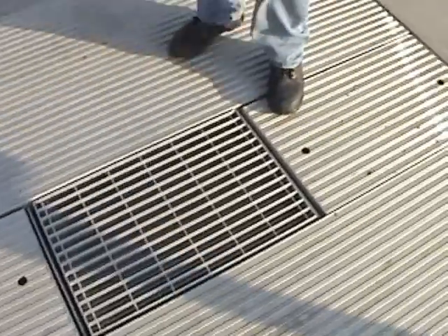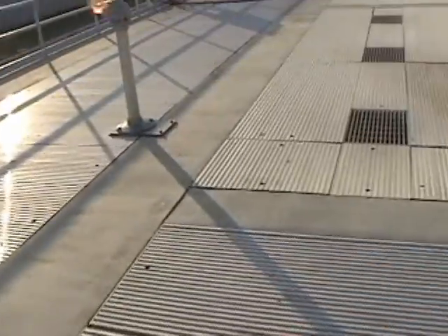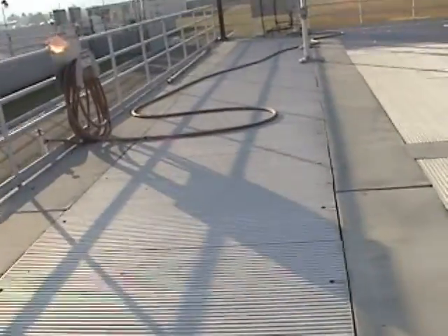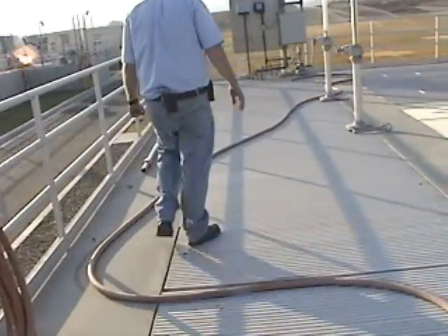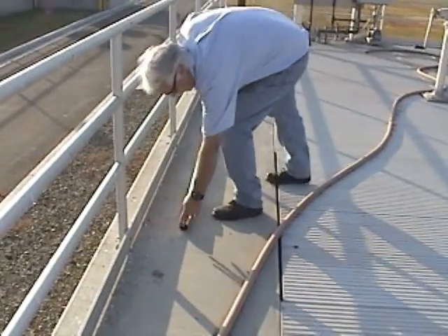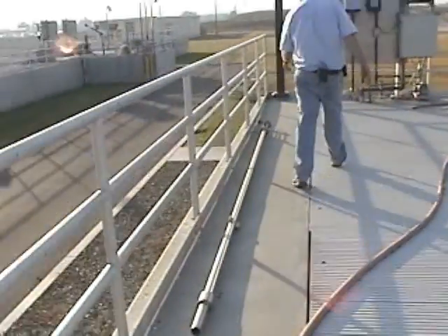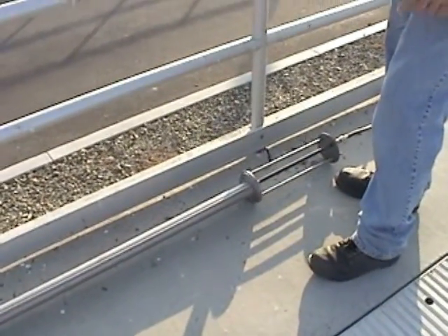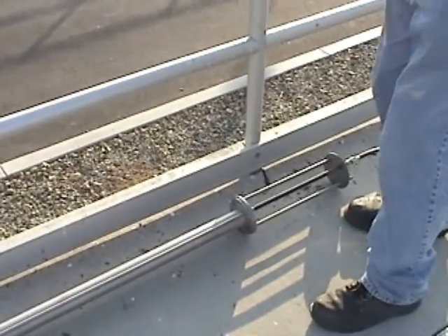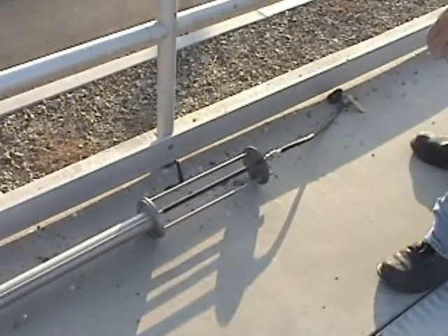So we've had real good luck with this. We thought they'd be plugged up all the time, and it hasn't happened. That center tube, there's one of them laying right over here. And the sand, which is the filter media, is picked up right through the bottom of this tube, and then it's pumped up all the way to the top. When it reaches the top, it goes through this insulator structure that sets up a motion in the water, which causes the sand to shake and release any debris that's on the sand. Then the sand flows over the top of this and back down, and drops back onto the surface of the filter. And here's the air line to it.